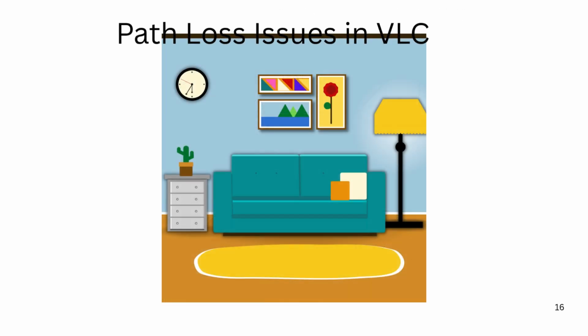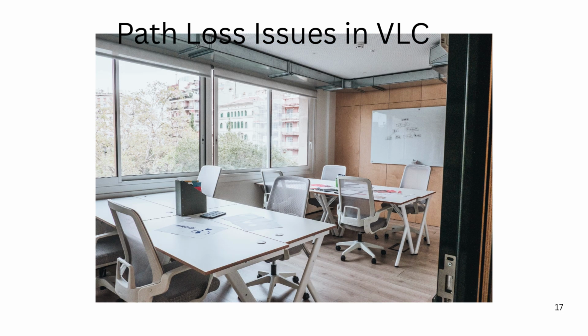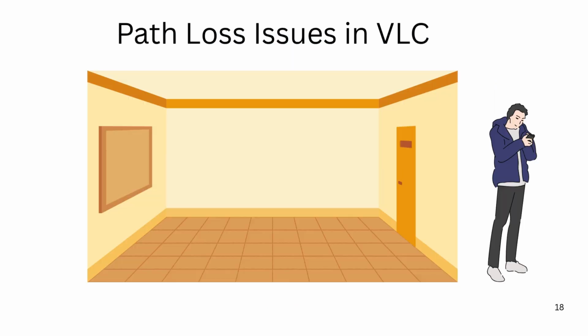Nonetheless, visible light channels are highly susceptible to frequent propagation path losses and can deteriorate the communication performance. Here, we are assuming a very ideal condition just for understanding all important VLC enabling parameters, but in practical scenarios, light signals significantly deteriorate due to different types of environmental challenges, such as walls, furniture, and even a human body can weaken the signal up to 40 dB.